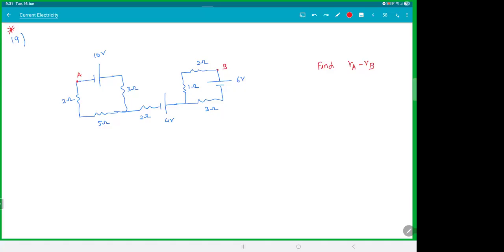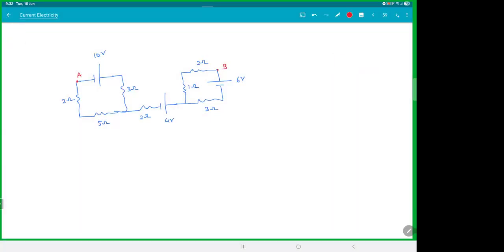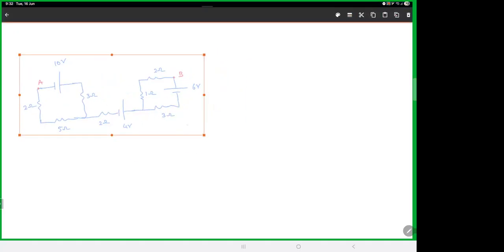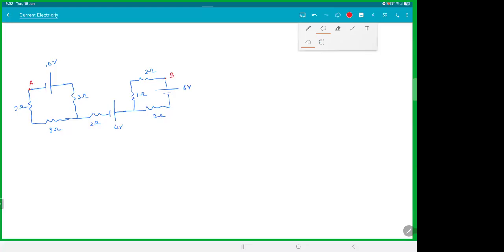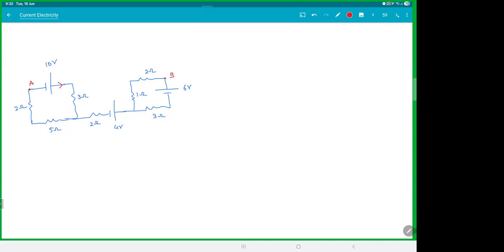Okay, did you guys notice something? The most important catch in the question is this. Again, going back to that argument, I keep telling you this every time: a battery does not produce charge. If a current I comes from the battery, it has to go back to the battery. Now with that in mind, let's say this battery is giving current I. As the current I is coming here, imagine some current small i goes here. That means the remaining current I minus i will go here, and this current will be I minus i here. That means you're getting only I minus i back in the battery.